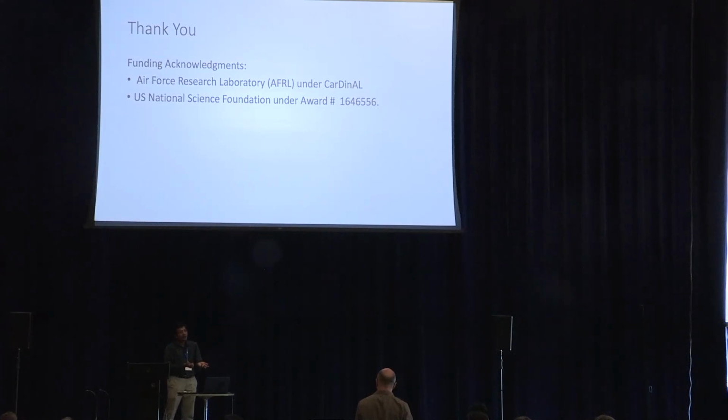Now, what's the right disturbance set to choose? That's something we couldn't figure out. We have some fixed numbers in the paper, but not more than that. Ideally, we need to account for wind disturbances, and we also need to account for unmodeled dynamics. Most control is not done under the robust setting, so it's very difficult to get references from other papers on what they use.